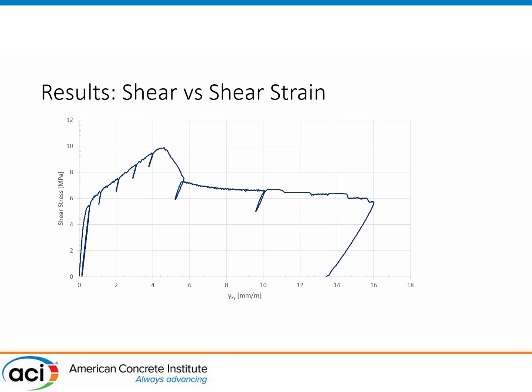So even out here at 1% of shear strain, which is enormous, we had 6 megapascals being resisted, 4 of which could have come from the internal steel. So the fibers somehow kept on working, actually, even after we had very wide cracks forming. So that indicated significant ductility in the response. And then finally we unloaded, because we were now getting worried that the displacements were too large.